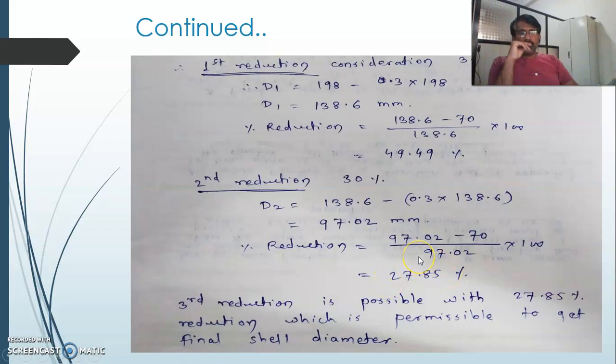If we consider the earlier 45% reduction, then cracks may develop and the drawing operation will not be perfect, because the second draw reduction will in that case be 35%, and we cannot apply 35% in the second reduction. So it may be quite difficult to go with the first possibility. The second possibility is good and we can start our operation in this sequence only.